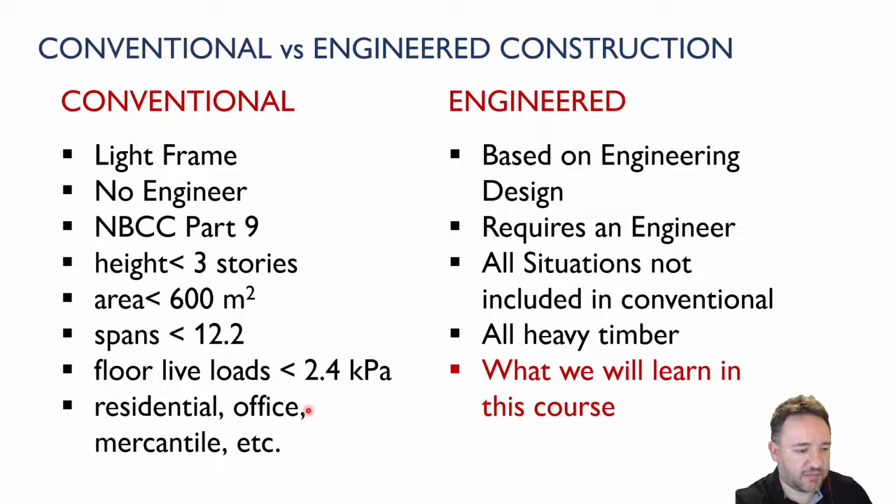Okay, so in the NBCC it's Part 9, in the OBC it's Part 9, and this basically gives a bunch of prescriptive rules for how exactly to build something out of light frame timber. So these are how long things can be. If you have a certain kind of area and you have a certain span, you have to use this beam, you have to do this kind of detailing, et cetera. So you don't need an engineer because all the engineering details are built into the detailed rules for building that structure.